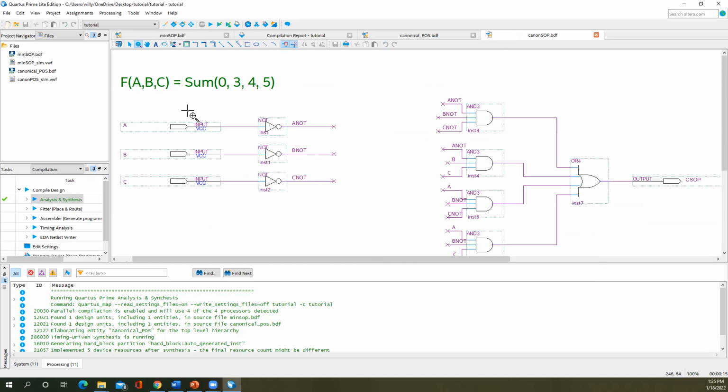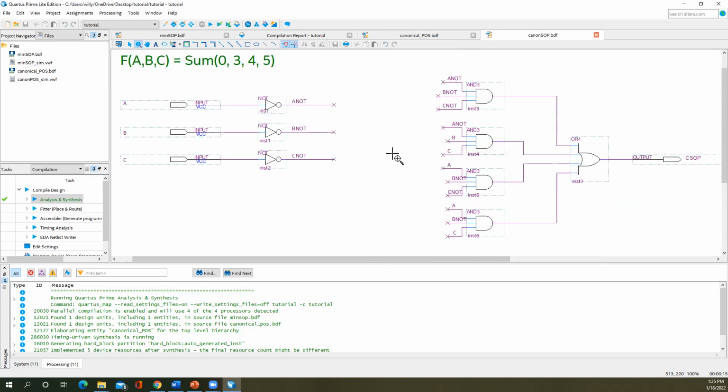All right, so this one I already drew so that we don't have to go through drawing it again. Again, I use the text tool to remind me that we have 4 terms that should reduce to 1, right? We've got our inputs A, B, and C. We've got our signals A naught, B naught, C naught labeled here. Sum of products, our product terms are these AND gates. These AND gates have 3 inputs, right? Because we have 3 input variables.